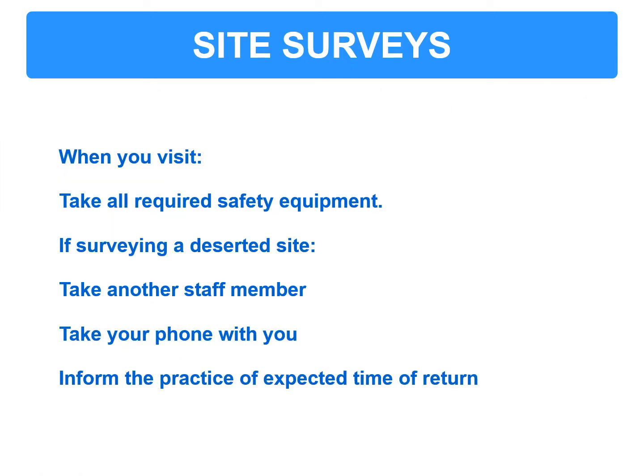So when you're visiting, take all the required safety equipment, personal protective equipment, gear. If you're surveying a deserted site, take another staff member, if at all possible. And usually you'll need 2 people to carry out a survey if you are taking a dimensional survey anyway.